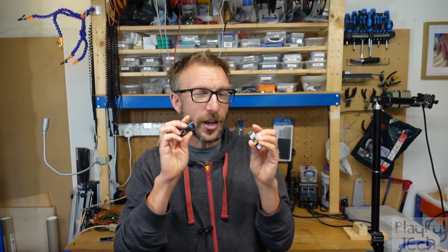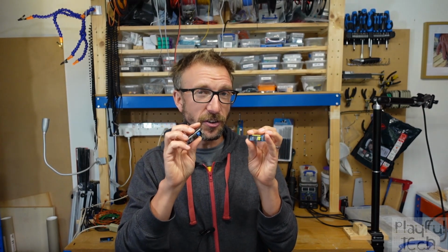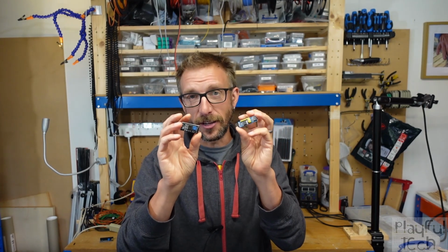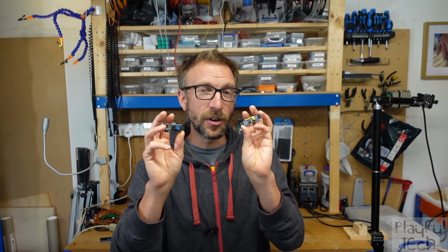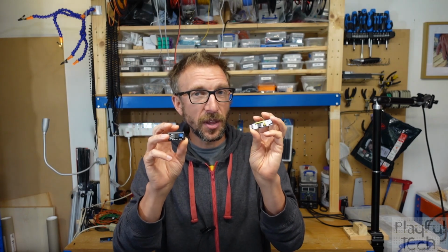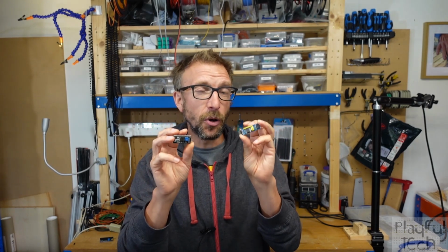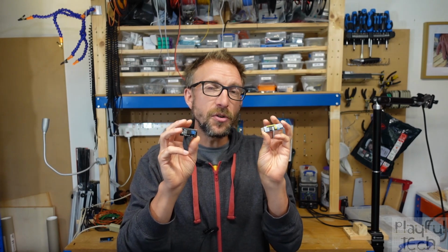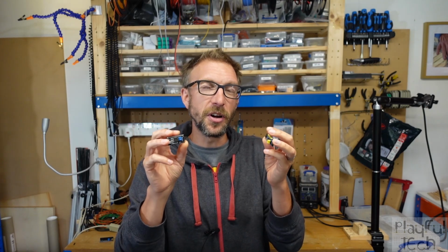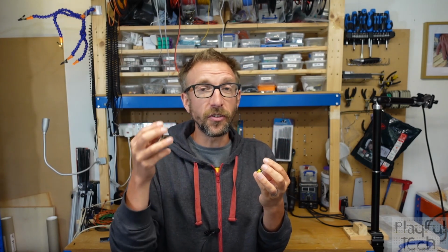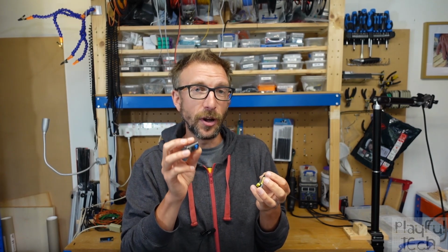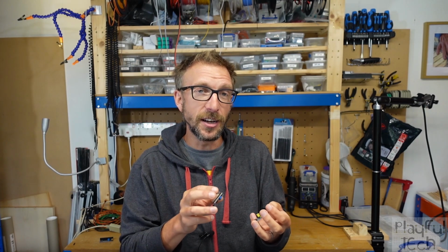Now, they don't quite have the same capabilities as built-in GPIO pins though. For one thing, they are digital only, so you can't read an analog input on these pins, and you normally can't write a PWM analog output either. And they also don't have built-in pull-up resistors. So you can set them to the equivalent of the input or output pin mode from an Arduino, but you can't set them to the equivalent of input pull-up. You'd have to explicitly add external pull-up or pull-down resistors into your circuit, as I showed you earlier.